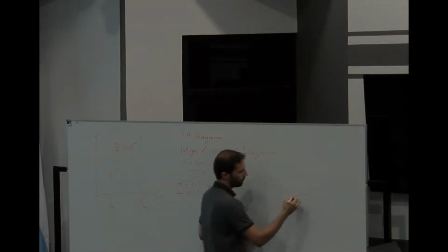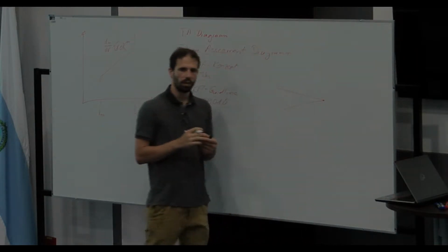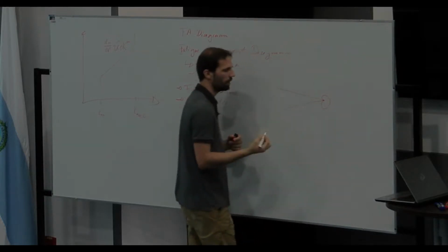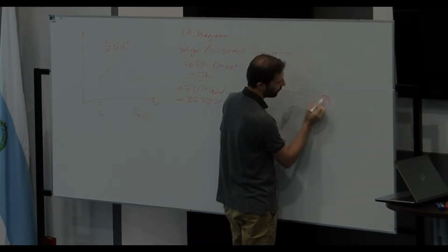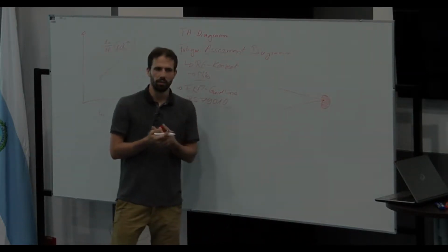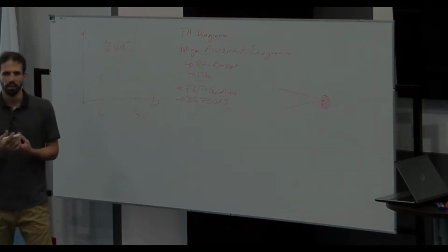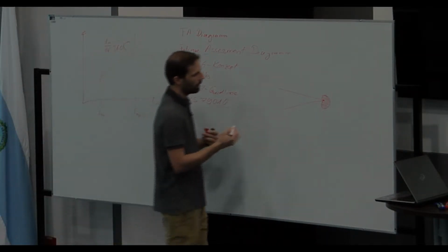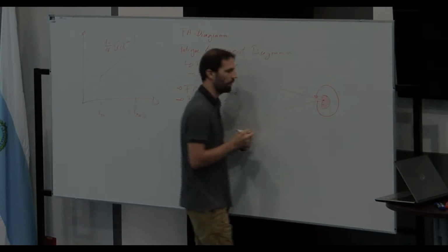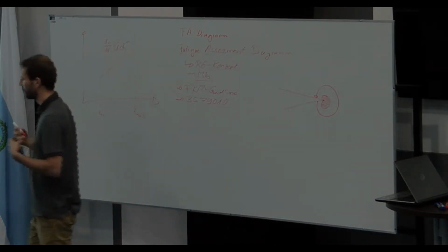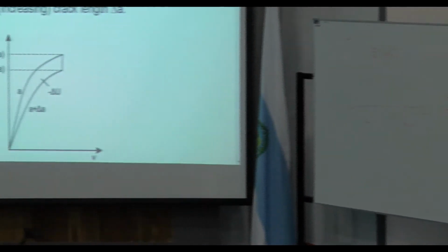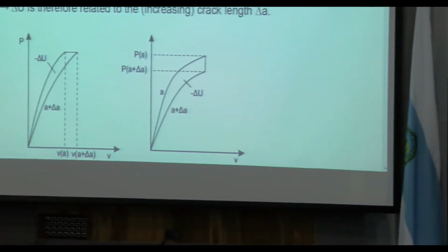We have our crack tip, and due to our plasticity, as you're also going to see in the videos, we have some plastic zone. And due to the plasticity, you cannot evaluate by just analytical information. So you have to go with an integral, and this integral, which is defined here by the circle, is also giving you the information about the deformation at the crack tip.